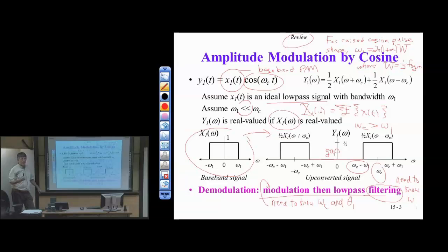When alpha is 0, we're back to the two-sided sinc. And when alpha is 1, we have full cosine roll-off. All right, so that's our first channel. So let's move on to the second channel. And of course, back to the receiver, we're going to have to do carrier frequency estimation and correction and some sort of phase-lock loop.